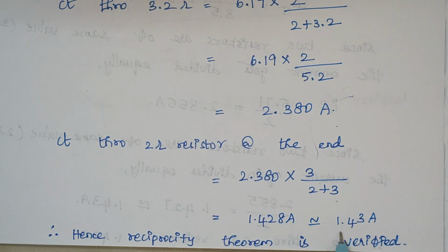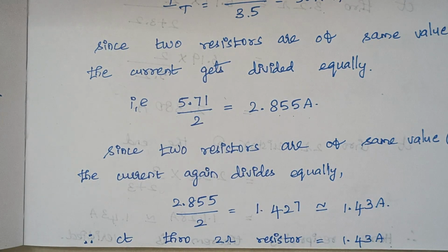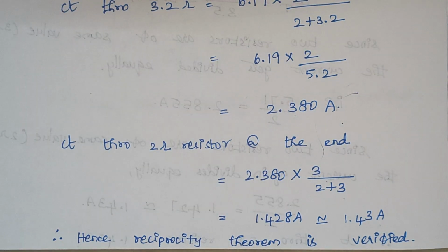So our final answer is 1.43 amps when you compare this with the step 1 answer. Here it is again 1.43 amps, right? Therefore, we can say the reciprocity theorem is verified.